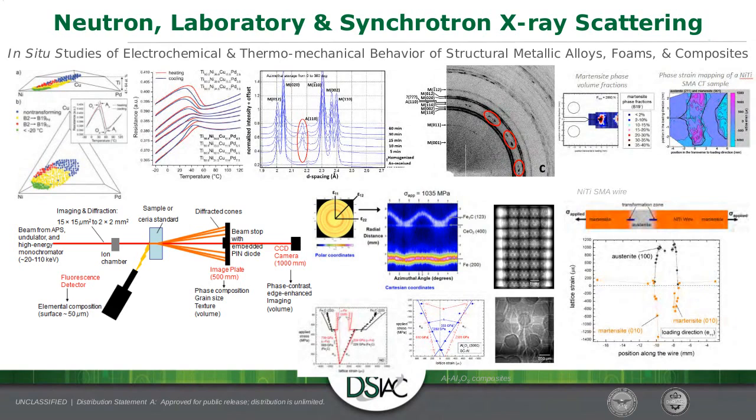And so what they do with that is they'll have it in a cryogenic temperature, and then you bring it out, put it on the part, it'll clamp down, and then you're ready to use it. And the way that works is the niobium sort of forms a soft phase in between the shape memory alloy, and so that sort of gives you some elastic range to work with before you take advantage of the shape memory effect. So that's for coupling materials.